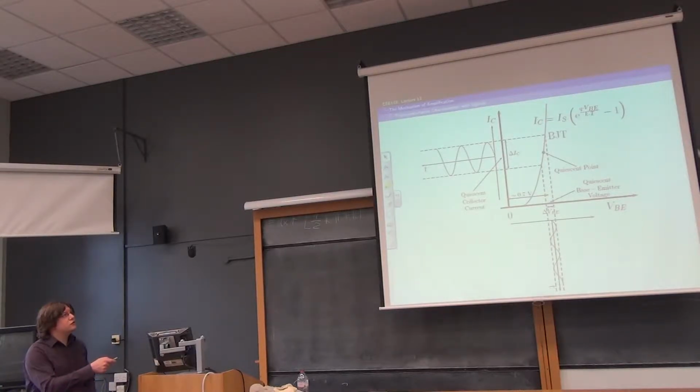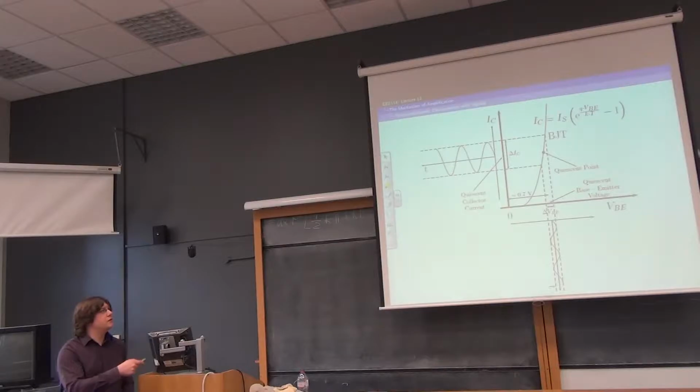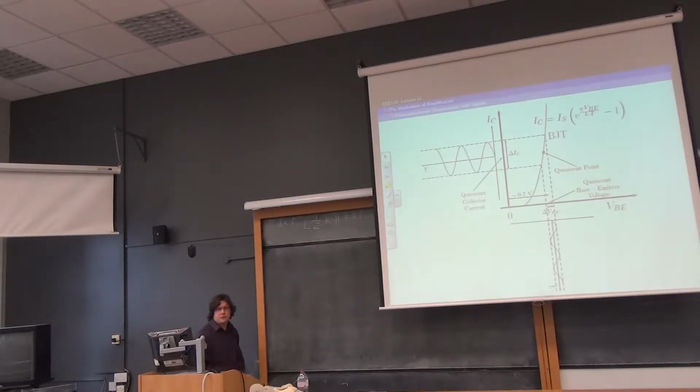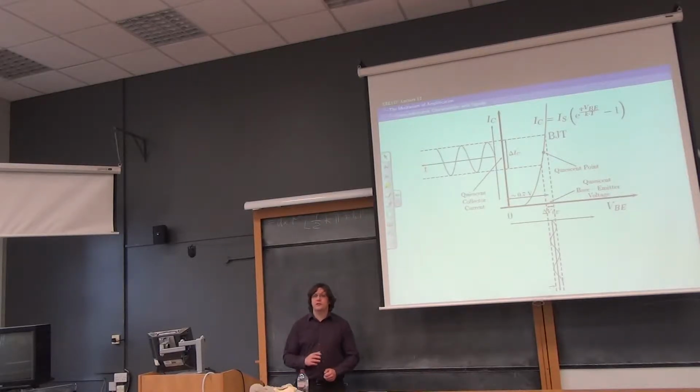So you could actually draw a similarly shaped graph, where you've got sine wave in and sine wave out, on the output characteristics if you wish. But I prefer to do it on the transconductance characteristic, because I said a couple of lectures ago that transconductance is the sort of mechanism by which all amplifying devices can ultimately be described. And the output characteristic, you can talk about base current if you want to, but that doesn't work for MOSFETs, so I'd rather look at it like this. Anybody want to hear that again? It's fairly important.